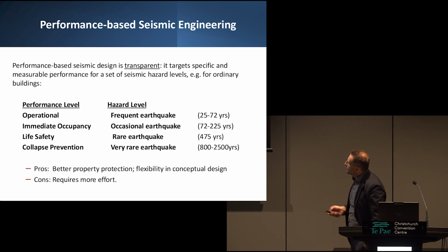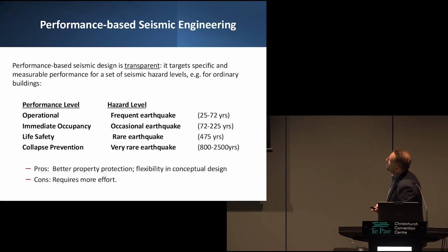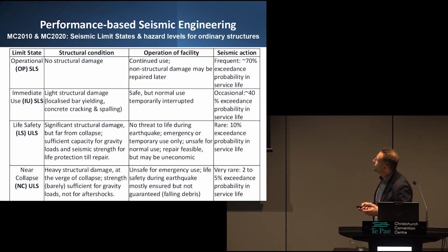And then obviously the model code has a probabilistic basis, and we also have to remember that most of the formulation relies on partial safety factors on the material, while in New Zealand we tend to follow more the ACI approach where we have one partial factor.